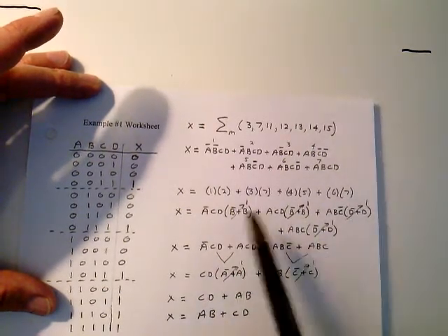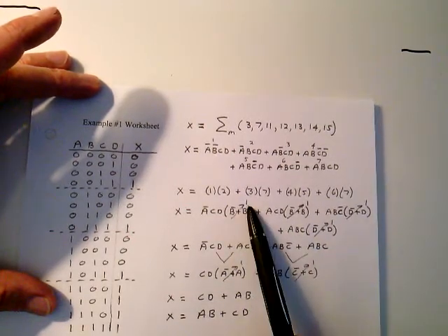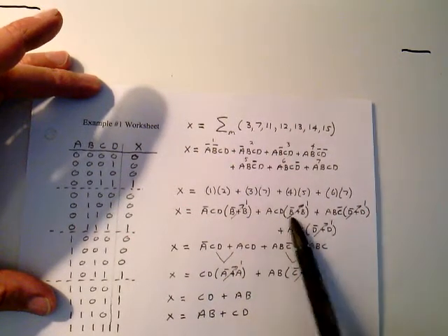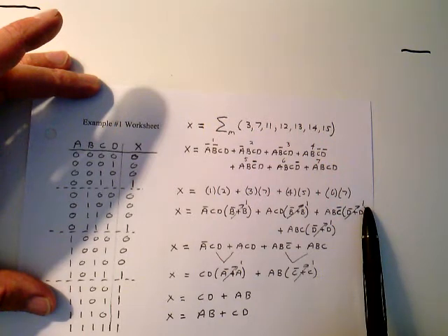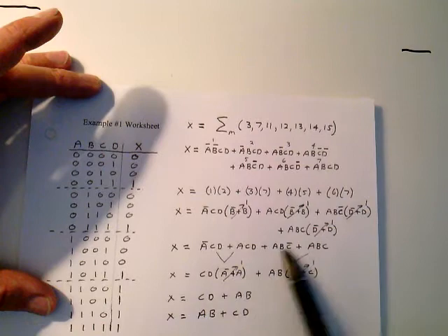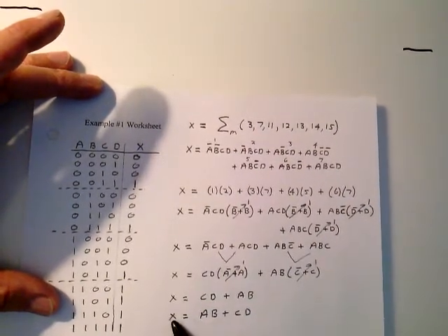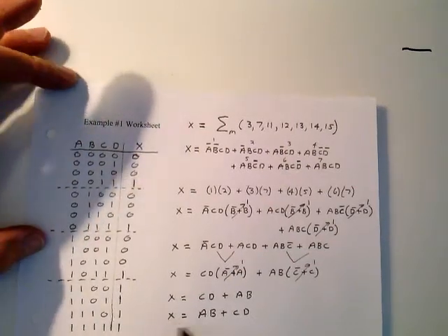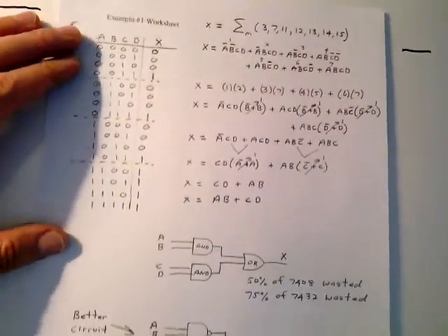When I do that, do you see these expressions all go to 1? I mean, B bar or B is a 1. You already have that memorized. D bar or D is a 1. One of these has to be a 1, and it's an OR function. So I can just proceed through my simplification here, group these two, and then rewrite this. And my output design is, the output is A, B, or C, D. And here's the implementation of it right here.